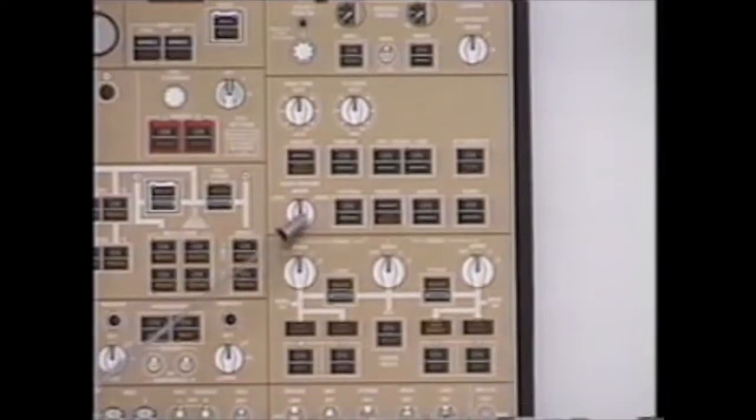Continuing our discussion with equipment cooling. Equipment cooling draws cabin air into the E&E racks downstairs below the first class and discharges that equipment cooling air one of two places, back inside the lower cargo compartment or overboard depending on the outside air temp. With the selector in normal, we're on the ground at the gate, engine shut down, outside air temp less than 45 degrees, the equipment cooling air will be discharged into the forward cargo compartment.